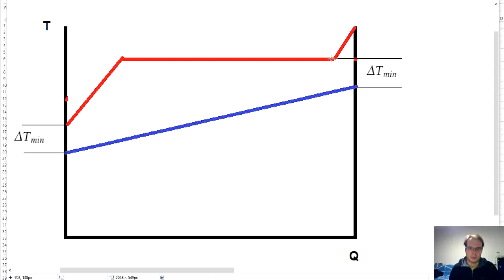We will assume a counterflow heat exchanger type, where on the other side of the heat exchanger there will be the minimum temperature difference between the inlet of the feedwater and the outlet of the subcooled condensate. So the condensate will not